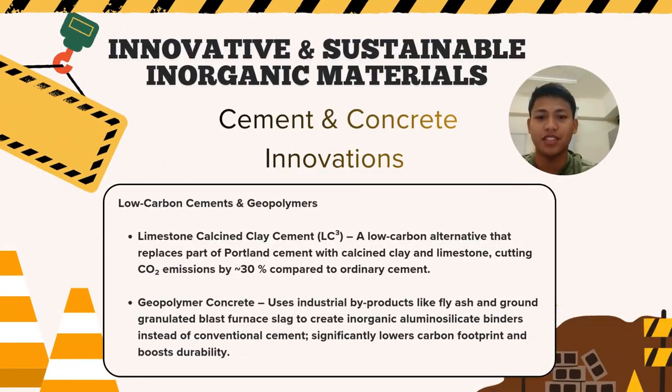So the next part is innovative and sustainable inorganic materials. The first material is cement and concrete innovations. The innovation is low carbon cements and geopolymers. Limestone calcined clay cement is a low carbon alternative that replaces part of Portland cement with calcined clay and limestone, cutting CO2 emissions by 30% compared to ordinary cement.